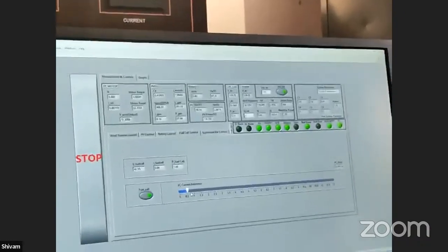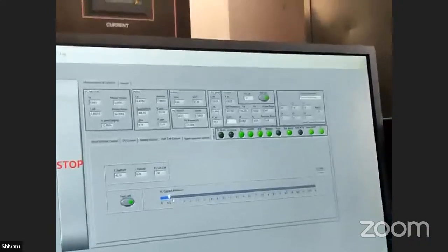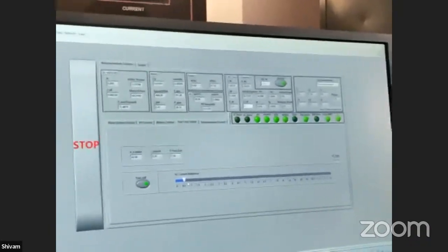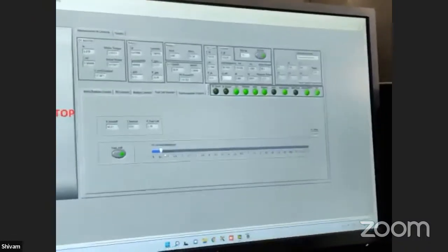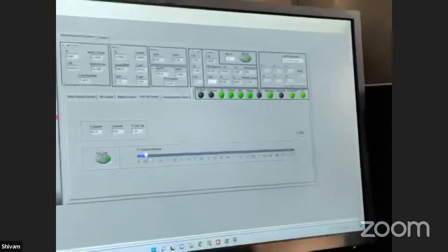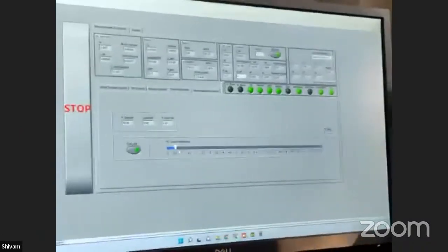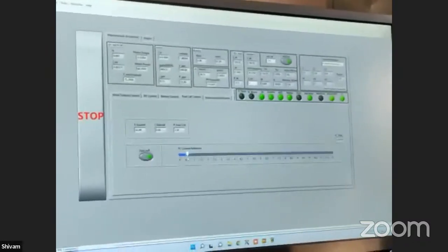So fuel cell is there for giving you a feeling of future source, but it is very slow. Response time of this setup is very slow. In comparison to PV or wind, this fuel cell is very slow in terms of its response. So you cannot rely simply on this for meeting of this load. So we will let it work.